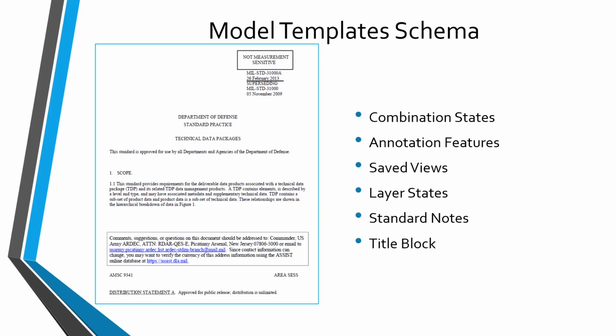One last thing I want to mention is that people say, hey, okay, all this stuff in here, what kind of reference can I use to figure this out? A great starting point is MIL-STD-31000. It's currently at revision A. If you do a Google search, you'll be able to find this on the internet and download it. They've got a great section in there about setting up the schema, or the organization, of your model templates in order to support model-based definition.